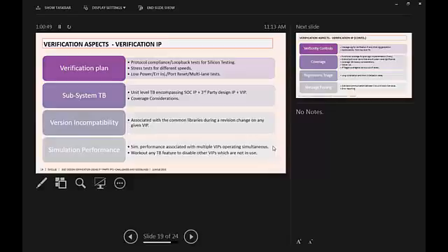Those can be emulated, because they also produce a lot of debug statements in the simulation log, which will bring down your cycles per second in the regression. So it is better to have those removed, because you are going to target only a few from the system level test. Removing all those components from the simulation is the better option to improve simulation performance.